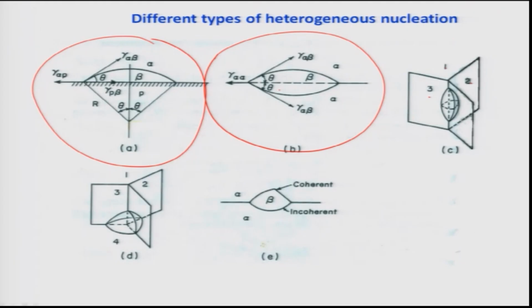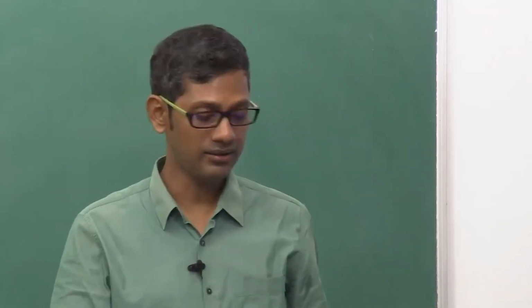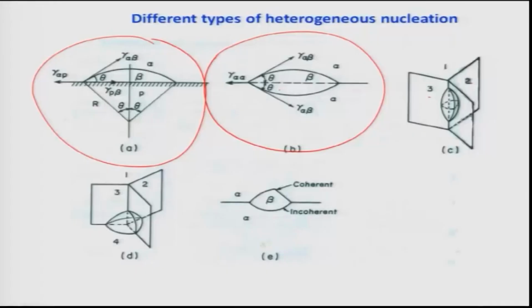So you can use this concept which I have just done for both single cap and double cap. You can extend that for the 3 cap situation and do the maths. Basically it will be again a factor 3 that comes into the picture. What happened to the grain corner? Grain corner is again not extremely difficult. Why? Because at the grain corner 4 caps are meeting. You see here there are 4 grains, 1, 2, 3, 4.